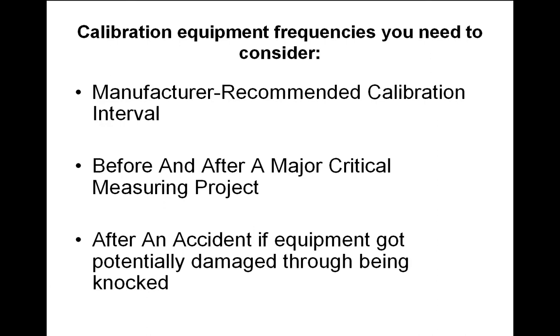There's before and after a major critical measuring project. If you've got a project which is very critical, where everything needs to be spot on, at the top frequency, at the top voltage or whatever, then you should calibrate before and possibly after the project as well, making sure that the equipment is still up to scratch. After an accident, if the equipment got potentially damaged through being knocked, or you drop the equipment, then you may think it's necessary to calibrate it just to be on the safe side.